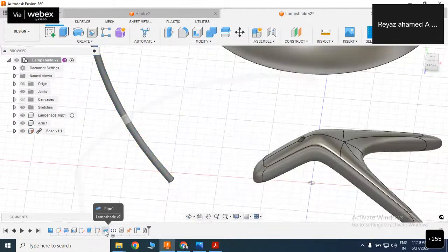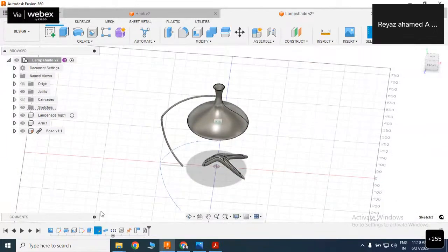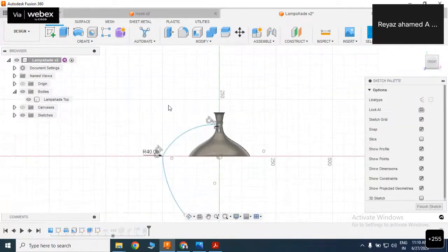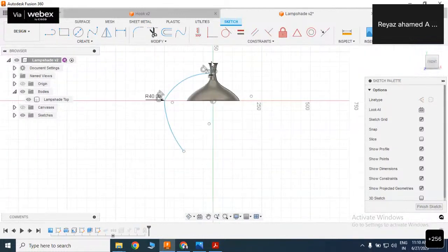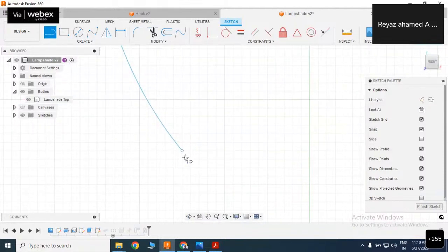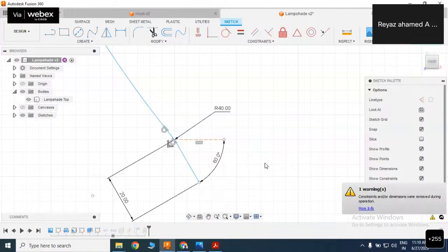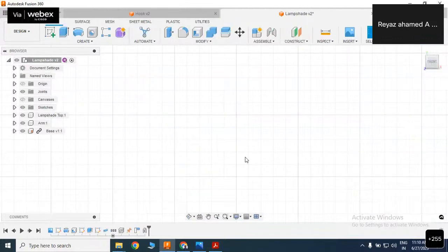See, here the pipe portion is there and then the sketch portion is there. So just select the sketch. Right click the sketch and then edit sketch. You can go to the path of that pipe. Here, the modification I'm going to do is create a line over here for the length of 20 mm, at an angle of 60°. And then just apply the fillet between these two edges, for 40 mm. Okay, just click on finish sketch. That's all. Only one modification we did.